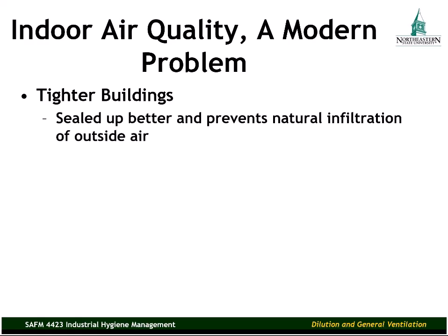And prior to the improvements in building technology, a lot of the ventilation, the general ventilation that occurred, was through openings in the building. There was a natural infiltration of outside air. So with tighter buildings, we've had to be more aware of the potential for indoor air quality problems.